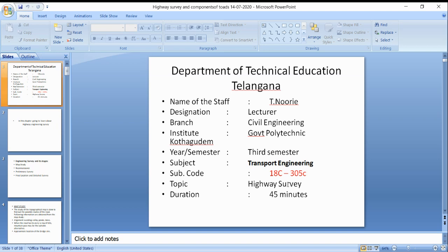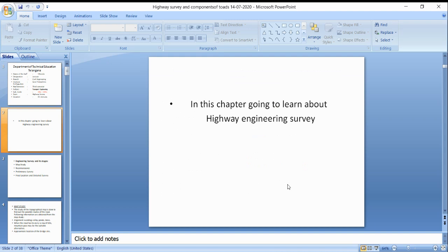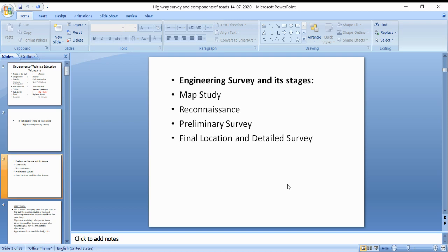If there is any lake, it should be avoided, as the straight alignment has to be changed. Where there is a lake, the cost of the bridge or a culvert is also important. We have to see the cost of the whole structure, and then only can we decide whether to go for the short route or for another route, with a deviation.